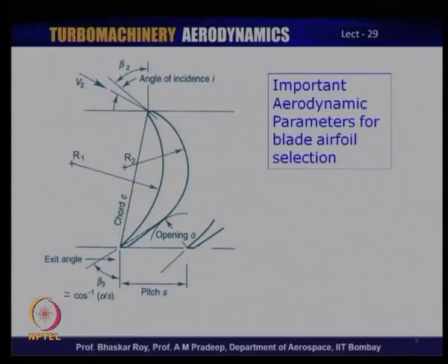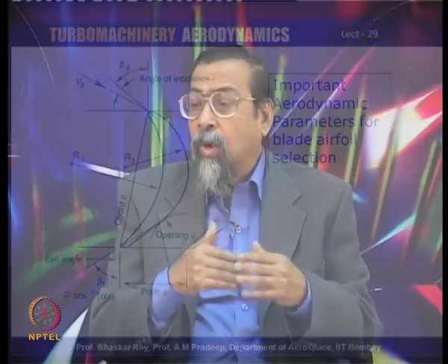Indeed, what should be the surface area of this surface and the surface area of this, to allow for sufficient contact between the blade surface and the gas which is passing through, and that contact, as you know, transfers the energy from the gas to the blade. So, there has to be sufficient contact on the surface between the gas and the solid body of the blade for effecting the work transfer.